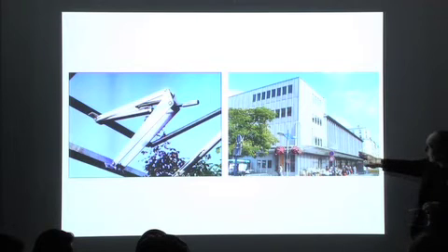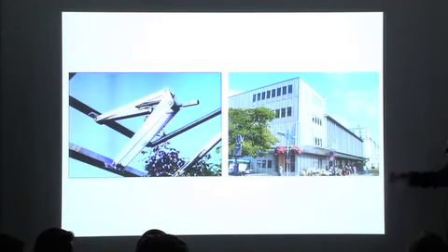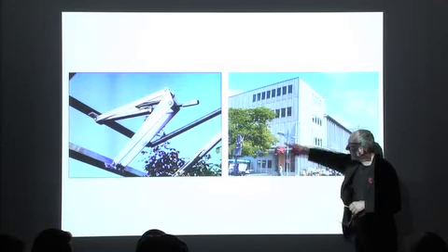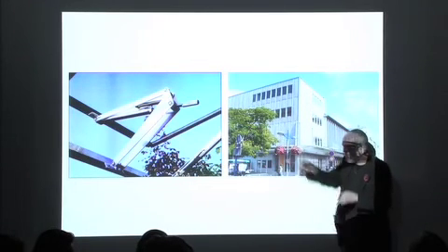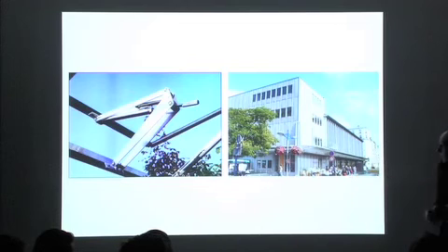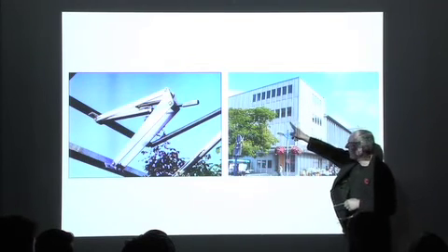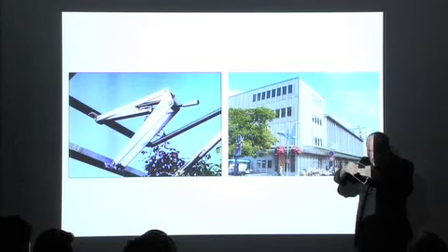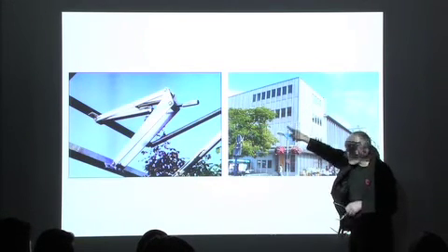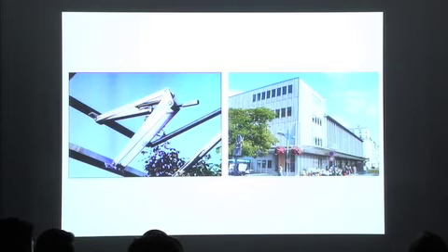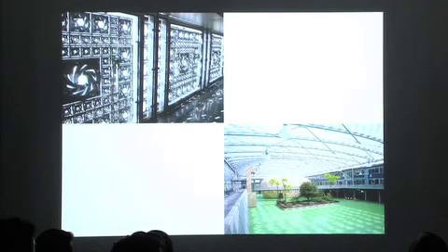And this is a building by Jean Prouvé, where all the cladding panels do the same sort of thing. Rather than make what we do now, which is expansion joints to allow differential movement for different materials, Prouvé just said, well, these panels can sort of pop. They curve out when they heat. So we don't need to have expansion. So it's a very dynamic facade. It actually changes shape when it gets hot. When it warms up, the whole facade slightly pops out and exaggerates. Solves the problem by a state change material.